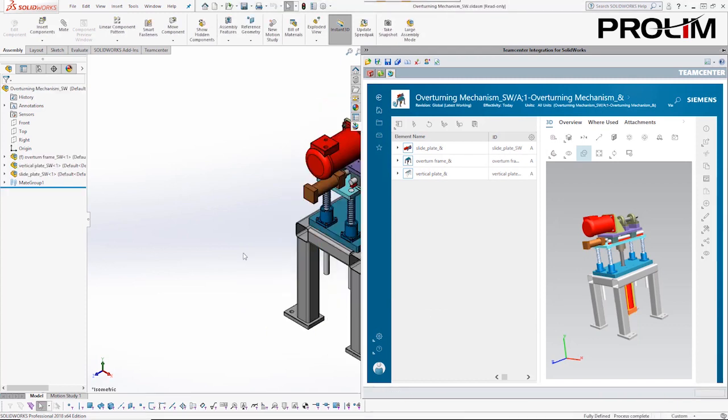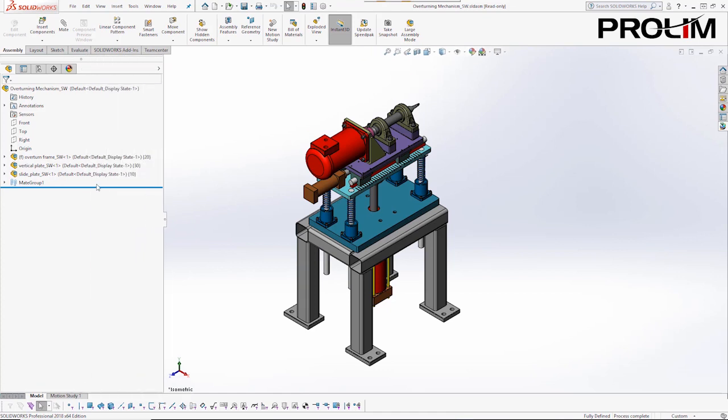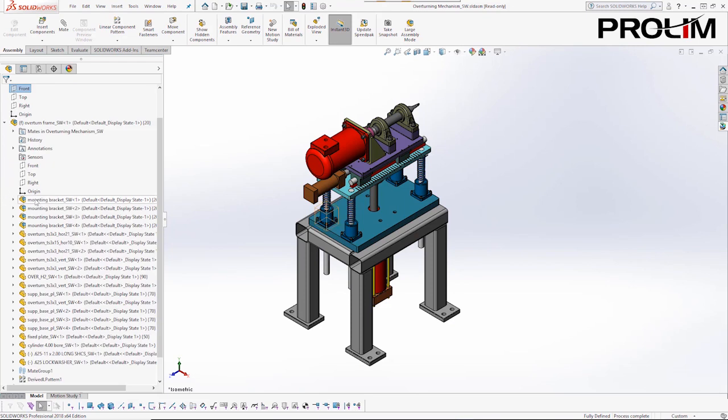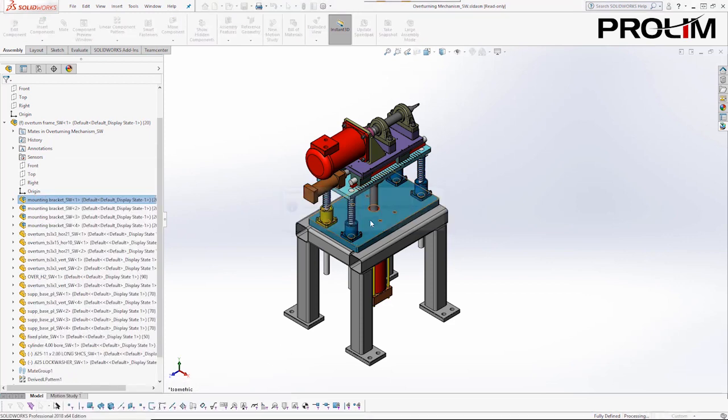Now that all required models are available in the SolidWorks session, the subassembly may be copied. The user has the choice to create an independent copy, a replacement copy, or an occurrence-specific replacement copy. In this case, he will replace both occurrences of the subassembly with its copy.